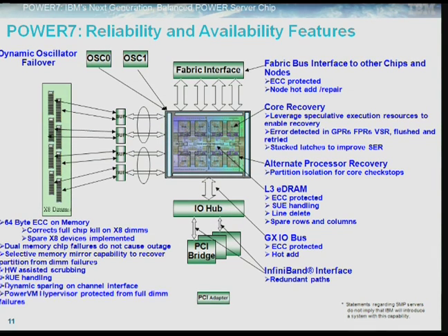In the event of a device fail, the memory controller can transfer corrected data to the spare device with no impact to the customer. Combining the new 64-byte ECC with a spare device provides protection against double device kills on a by-8 DDR3 memory.